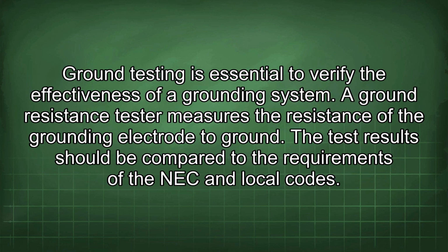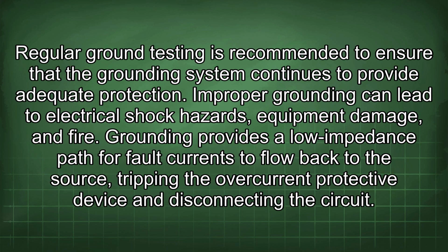Ground testing is essential to verify the effectiveness of a grounding system. A ground resistance tester measures the resistance of the grounding electrode to ground. The test results should be compared to the requirements of the NEC and local codes. Regular ground testing is recommended to ensure that the grounding system continues to provide adequate protection.